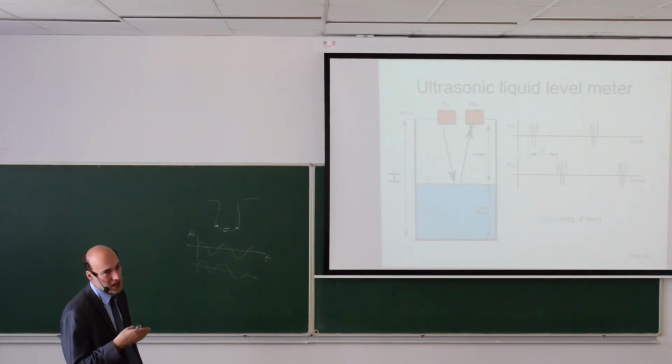This time difference is proportional to the distance between the sensor and the interface, and also to the speed of sound in the particular environment, but we assume that this is a constant value, or we can measure the temperature. So if the liquid level is changing here, if it is getting smaller, then the distance between the sensor and the interface is getting larger, and we can measure what is the liquid level in the tank. So this is the answer for the question in the test. We're not looking for amplitude, but we are looking for the time delay between the transmitted and received signal.